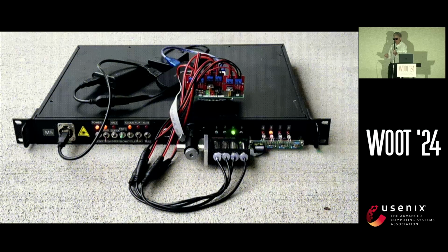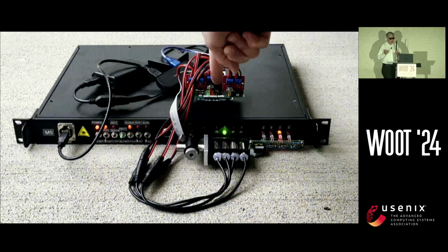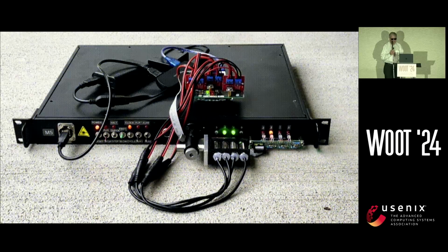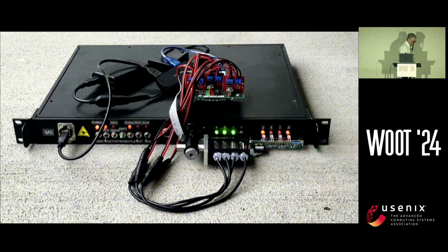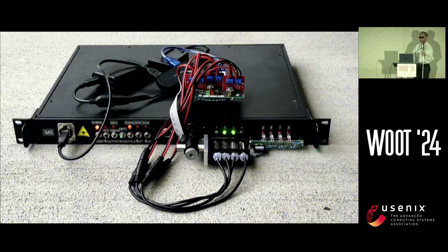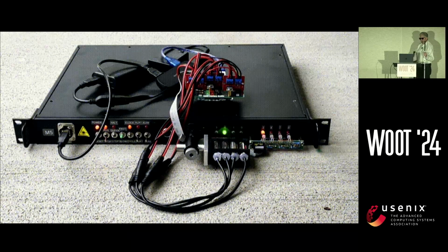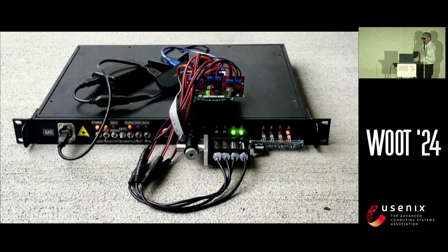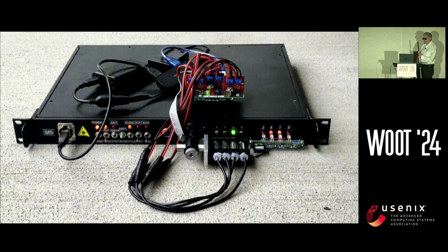The attacker watches the system in order to learn the cycle time and get a phase lock on the internal state of the CPU. This is possible because the accumulator display always changes at a known offset in the microcode cycle, which might be different for different instructions that can change the value of the accumulator, but the attacker can tell the difference by observing the magnitude and direction of the change.